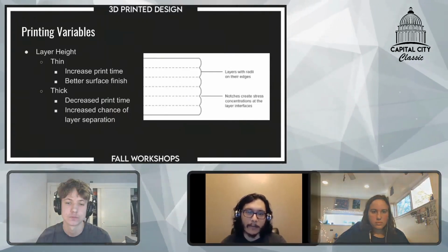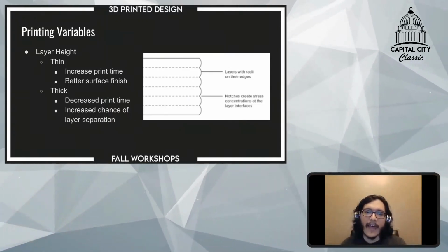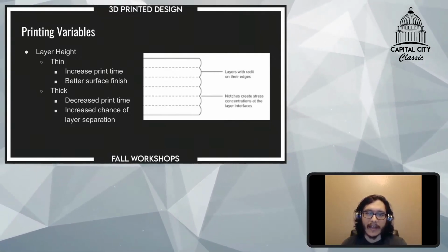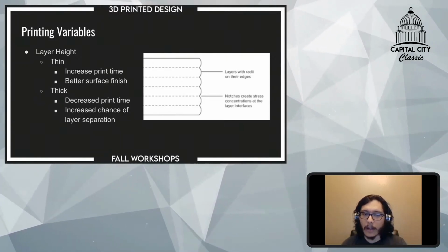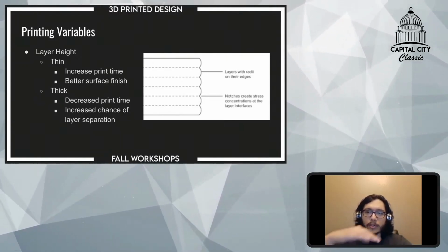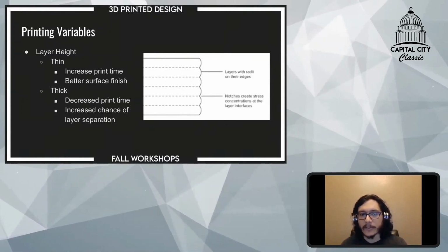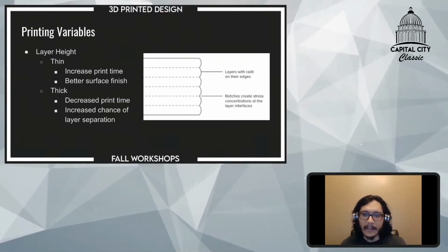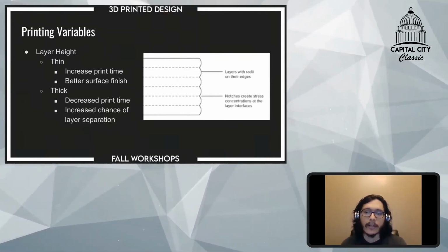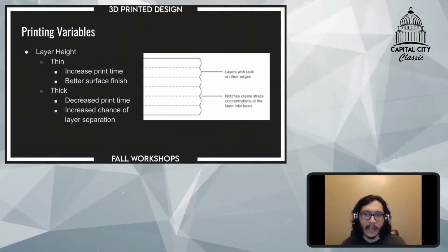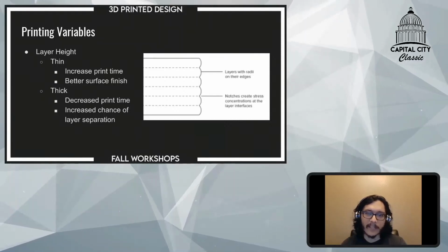The main problem with thick prints is that if you think of the extruder as extruding a circle profile, because you have two circles laying on top of each other, you actually end up with stress amplifiers between the layers, and the layer adhesion zone is already the weakest part of the print. So you're actually introducing stress amplifiers into the weakest part, which makes it even weaker.